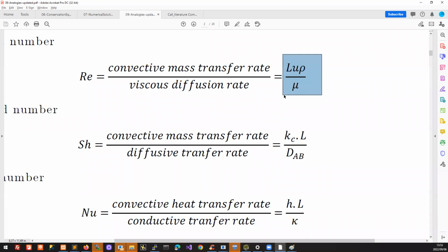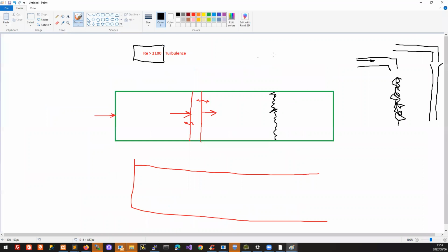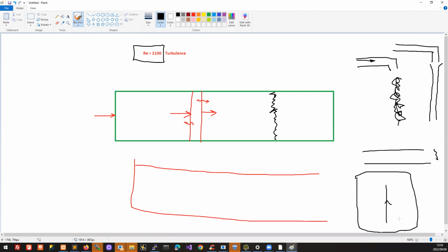And that means no matter what kind of situation you have, whether it's flow in some kind of pipeline and you are considering using different diameters of pipeline, or a big reactor where you've got some kind of fluidization or flow through there, you can have ridiculously different situations, but now you have one criterion. In other words, the Reynolds number is exposing something fundamental about all these different situations, and it's helping us to detect the onset of an important flow regime.